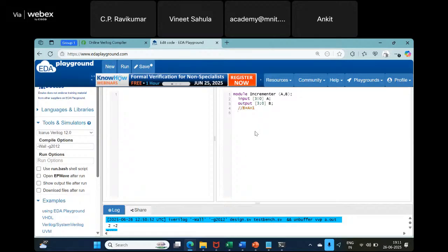See, if you just want behavioral code, then all you have to do is say always at A, B equals A plus 1. Okay, this will work. So we'll try here.